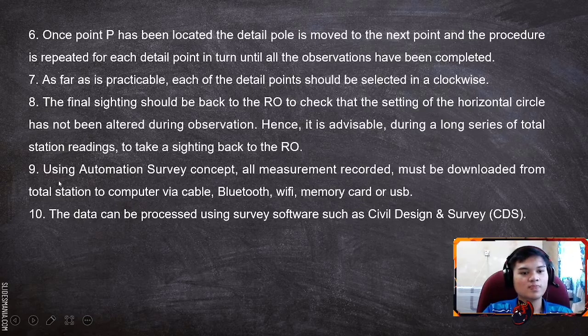Using the automation survey concept, all measurements recorded must be downloaded from the total station to the computer using cable, Bluetooth, Wi-Fi, memory card, or USB. And the final step is the data can be processed using survey software such as Civil Design and Survey, CDS.